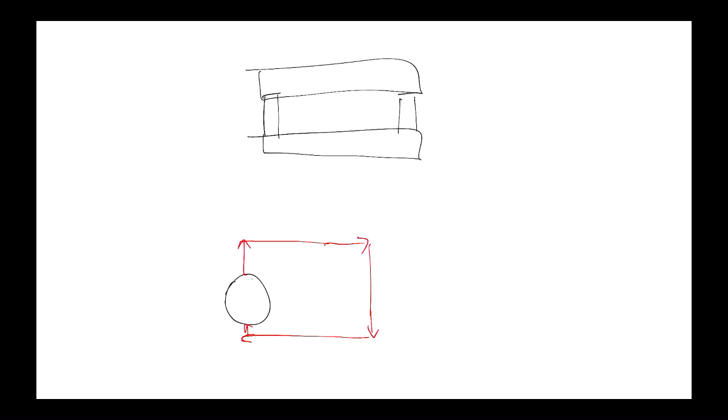Now, in order to avoid an obstacle, you need additional sensor info. And the sensor info is provided by three sensors on the front of the robot that are pure signals, bump sensors. So they are just either absent or present, indicating that it's run into something. Using these three sensors, you now have to design a state machine conceptually first.